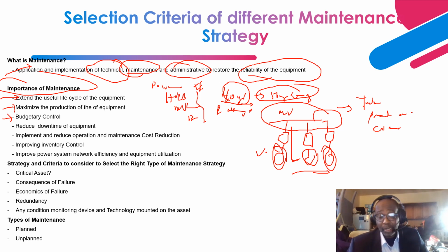another example I can give you is for the circuit breaker. If you don't perform the required maintenance on the circuit breaker, a typical example is performance of insulation resistance, a timing test, travel motion tests, and contact resistance testing. These are all very important tests that are done on the circuit breaker to ensure the reliability of the circuit breaker.